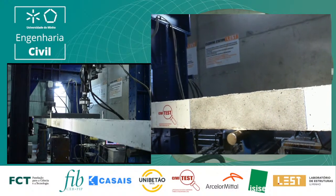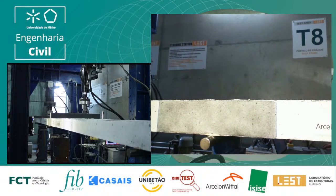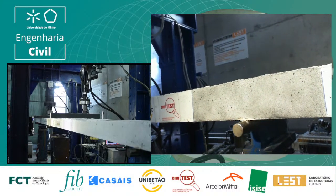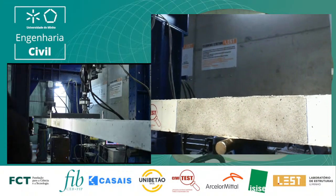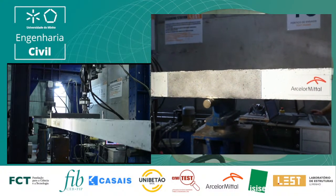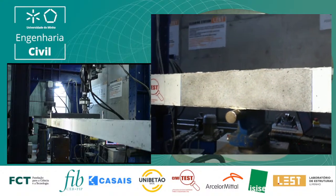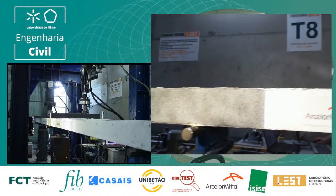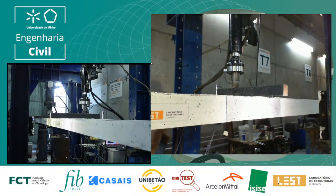We have relatively scarce material in this domain, and we expect to obtain with this test very important information for verifying the influence of fibers, not only for service limit states, but also for ultimate limit states, but mainly for service limit states. This is why we are using DIC to measure the crack width and the crack spacing here in the intermediate support region, as well as in one of the sagging regions.